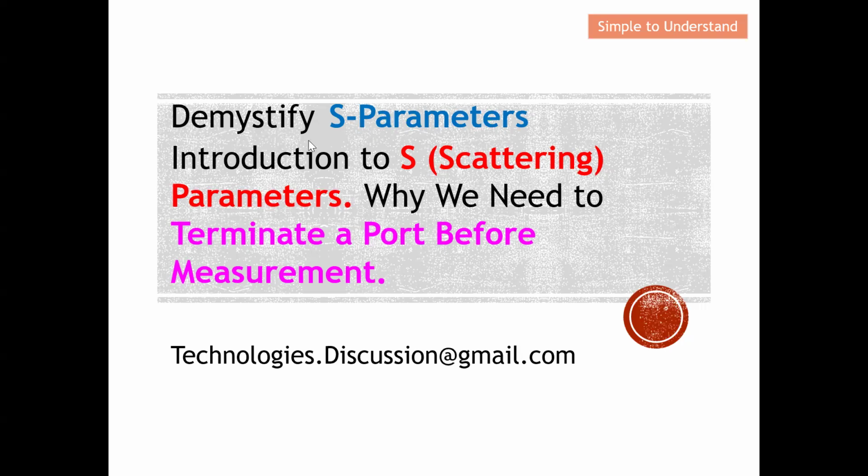Today, I'd like to continue the discussion on S parameter. On my first part of this video discussion, firstly, I will do a quick introduction. Okay, what is S parameter? So the word S actually stands for scattering. In this video, I'm going to explain why we need to have another set of parameters. Besides S parameter, we already have Z, which is also known as impedance parameter. We also have the Y, which is known as the admittance parameters. This video, I'm going to explain why we need to have S parameter. In short, S parameter actually has the application for high frequency.